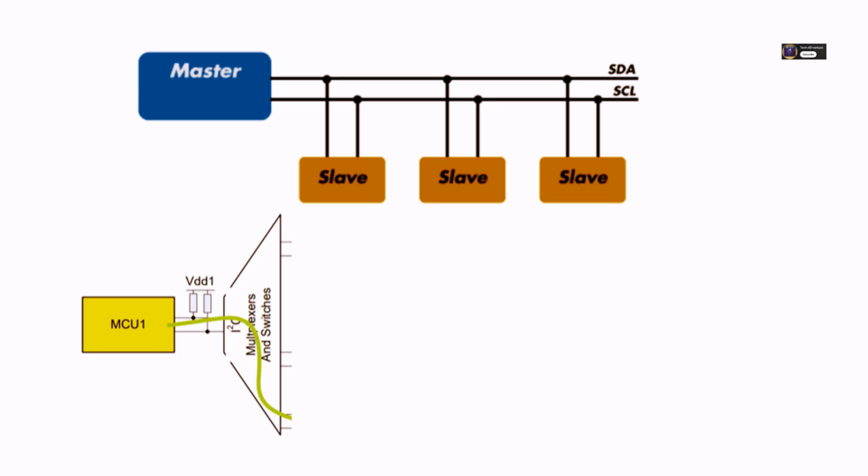Exactly. Another option, if your microcontroller has multiple independent hardware I²C peripherals, some bigger ones do, you could just put the conflicting devices on separate physical I²C buses. More complex, but avoids the multiplexer.